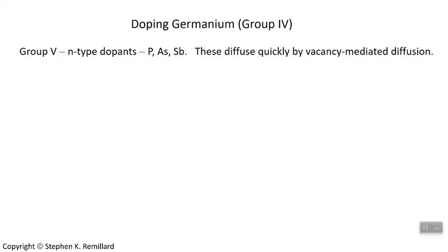And so how do you do it? You get the phosphorus, arsenic, or antimony to diffuse throughout the germanium, which you will do quickly during annealing, that is, during an elevated temperature stage of the preparation. Usually the most favorable thing is for a dopant to replace a vacancy. The semiconductor material, pure germanium, is full of point defects, and those vacancies get filled, and the dopants hop from vacancy to vacancy until finally they have diffused all the way through the semiconductor.